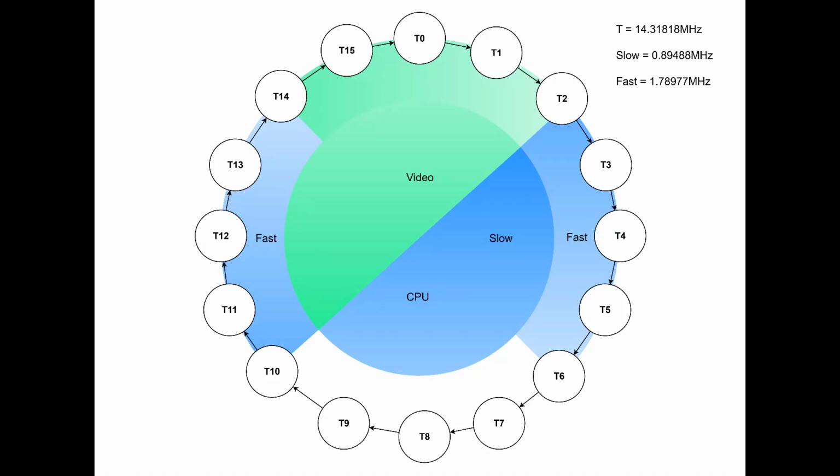This was originally the RAS signal, but I don't technically need RAS or CAS anymore, as I am explicitly and exclusively using SRAM. I have to manage the internal reset condition and how it affects the state, and, for those that have been listening to previous updates, manage the synchronization between the SAM and VDG. Historically, this was done by freezing the video clock until the right clock phase is reached, but because I'm integrating the VDG and SAM in a single device, I can now tell the VDG what state it is in, so it is the VDG that synchronizes rather than the SAM. Thanks to the faster access times for SRAM, I can also squeeze the fast mode to maintain a video signal.